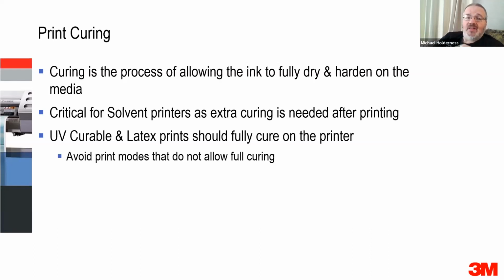Okay, print curing. It's the process of allowing the ink to fully dry and harden on the media. It's critical for solvent printers because you do need to allow that print to cure after it comes off the printer. Now, UV and latex prints should fully cure on the printer. It doesn't mean to say they will.